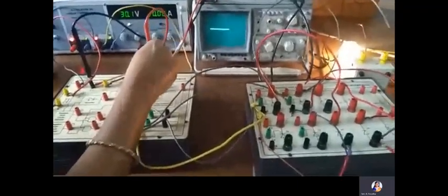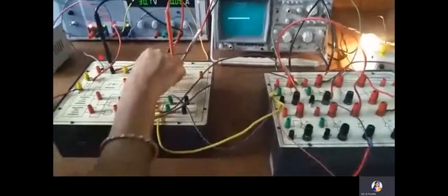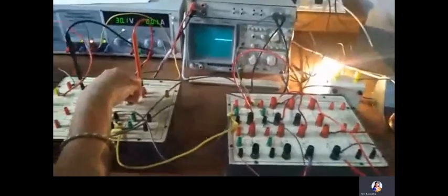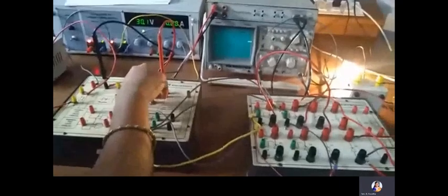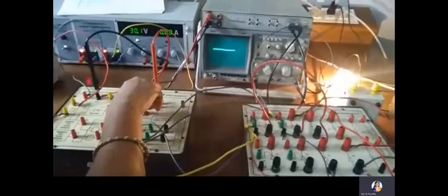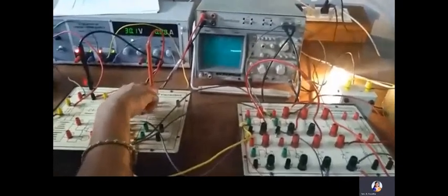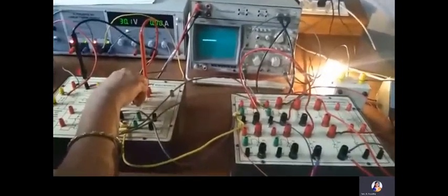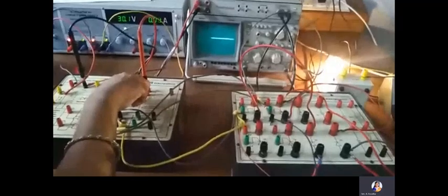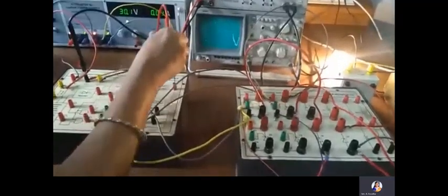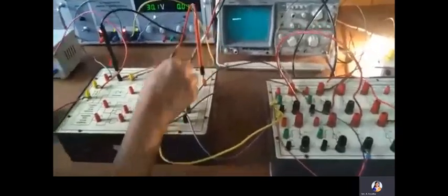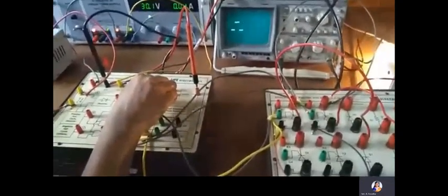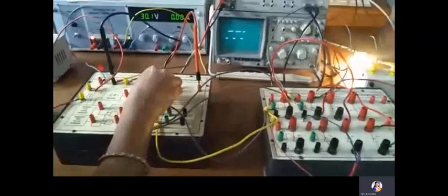Now, this E is the control reference signal. As I vary this knob, this E will be varied. You can observe the reference is moving up and down. The straight line is the DC reference. It's moving up and down. This is the reference voltage. Now, this is the firing pulse we have obtained after comparing the ramp signal and the reference signal. I am varying alpha here.